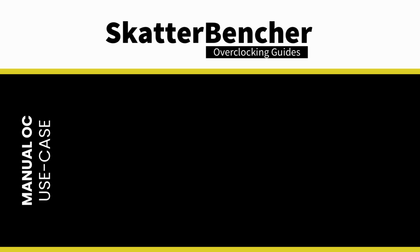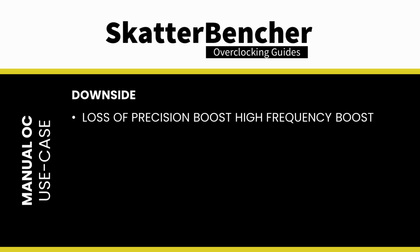Just like with all past Ryzen processors, the major downside of manually overclocking is that you lose the benefits of precision boost technology yielding high frequency in low threaded benchmark applications. So, whereas a 7950X can boost up to 5700 MHz with precision boost, it will be limited to your set fixed frequency when manually overclocking.